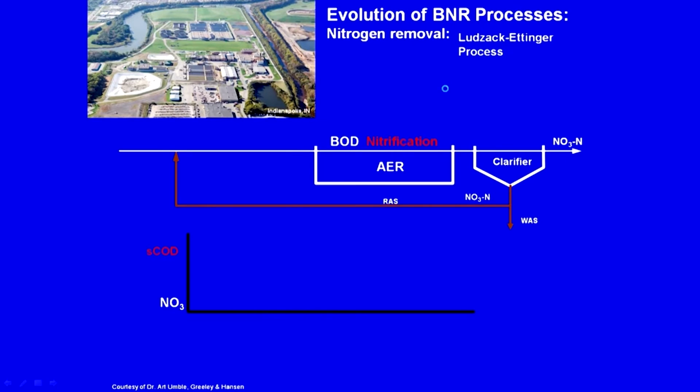Let us look at another configuration here. So, here we have the anoxic tank before the aeration tank, right, and let us see how the profile is going to look like. Theoretically, you will have denitrification, but when will you have, or what will be denitrified here? Whatever nitrate is coming into the picture, or the nitrate that is in this aeration tank which is being recycled will be degraded to N2. But obviously, the issue is that you will also have nitrates leaving the system, which is not something that you want. So, let us see what else or how this system is going to look like.